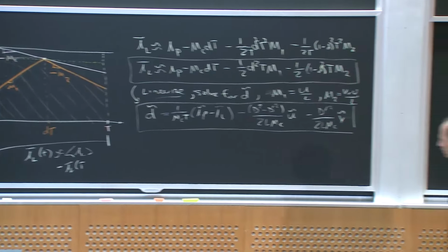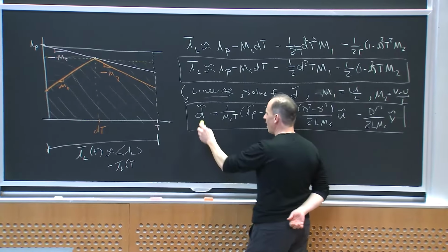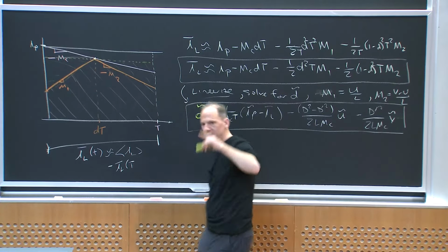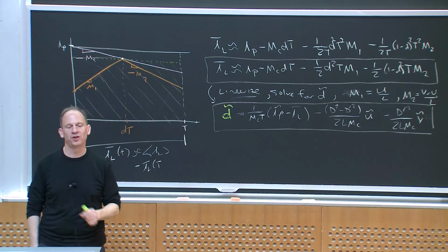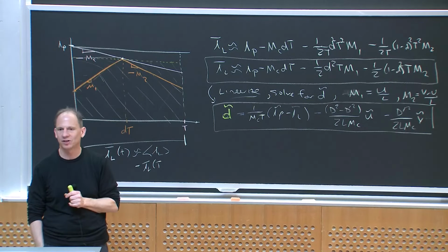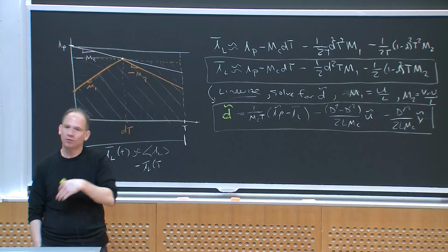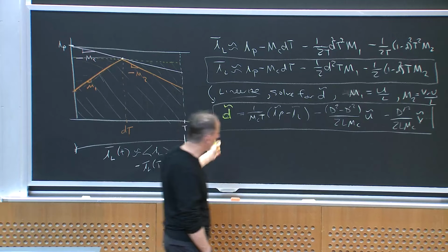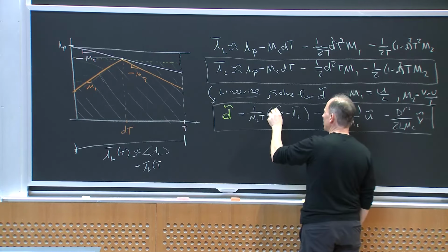So what's the point of doing this? The point is I can now substitute in for d tilde in my existing equations. And remember, d tilde was my control variable in all my existing state-space averaged linearized equations, right? If I substitute for d tilde, I get rid of d tilde, and all this other stuff is already in the equations except for I peak tilde.